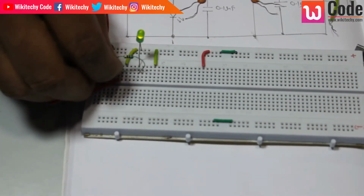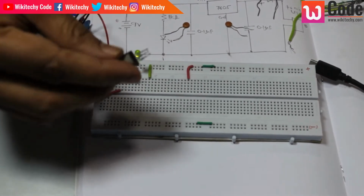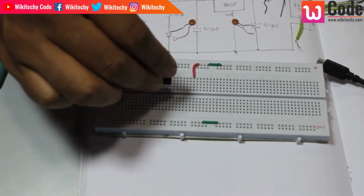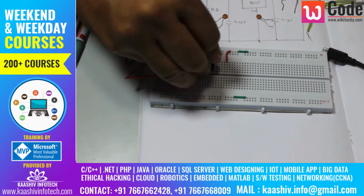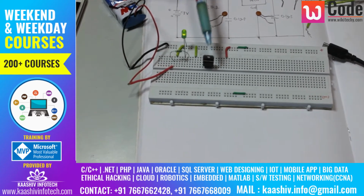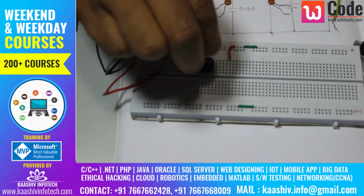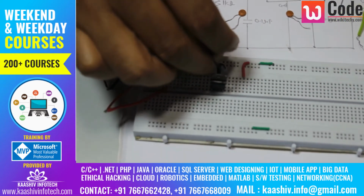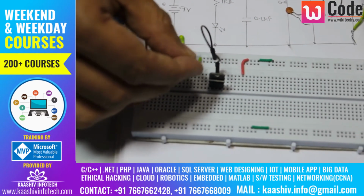That's pretty good. Now what I can do is, I need the voltage regulator. So the right direction is the input. So I connect it here. Okay, so this one is input, this one is output, the center is ground. So let me ground this one first. I need to ground this one, connect it, ground it, and I need this capacitor. We need to connect it and ground it.